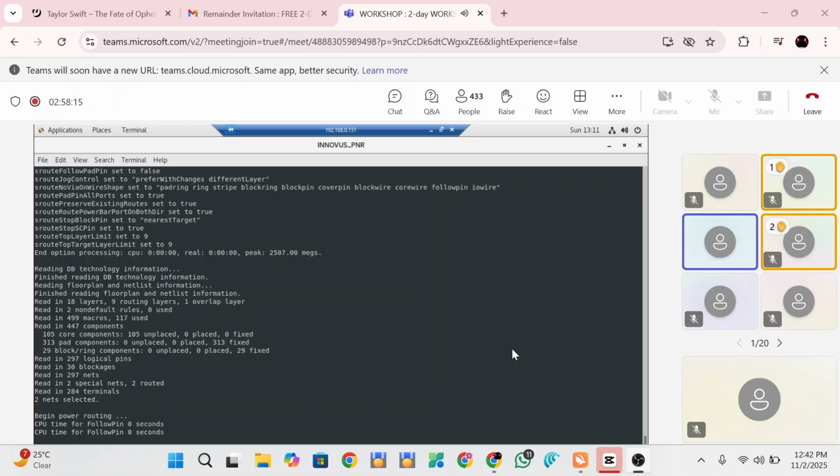Okay, you can see how these IO pins, the pins connecting to the board, will connect to the motherboard. Then there are power rings, these are the two power rings, VSS and VDD. How are they connected? These are connected like this. Again, see the structure to connect the stripes. In the middle of the macros, this is the power that will go from the top metal layer down to the bottom metal layers, and the bottom metal layers will be connected to the standard cells.